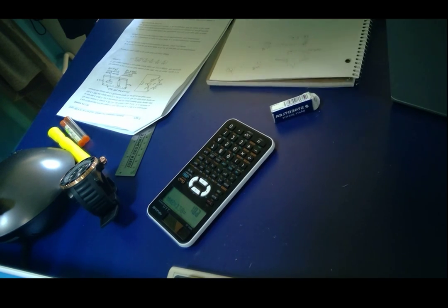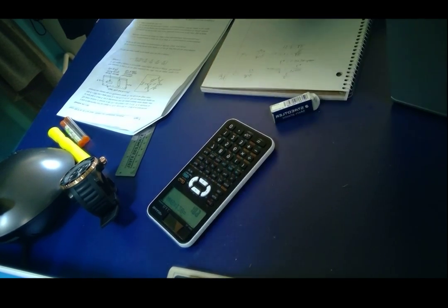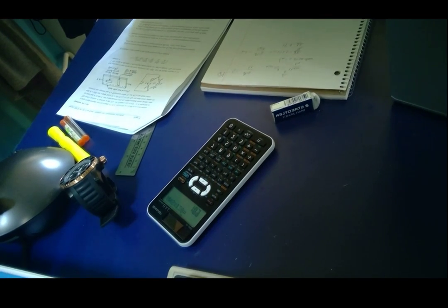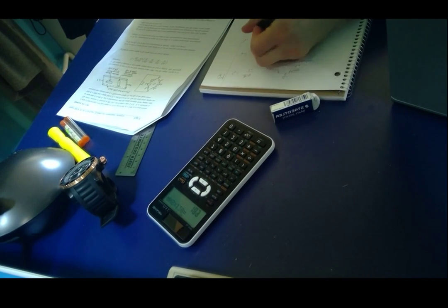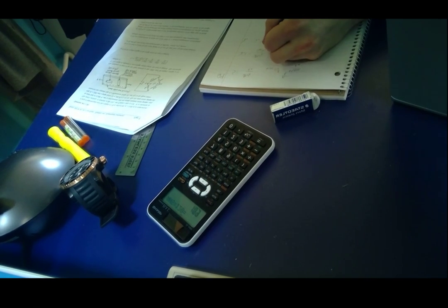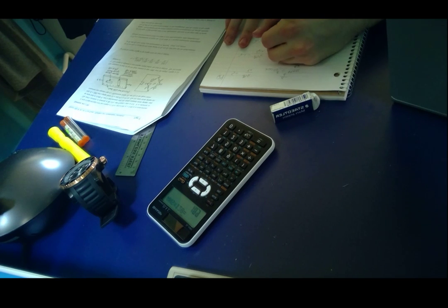All right. Well, let's just assume it is correct for now. So our V out is the V supplied, which is 2.5 volt. 2.5 volt times R2, R2 is 120, times R3, 120, divided by R2, 120, plus R3, 120. Oh, never mind. Yeah, it is 120 plus 120